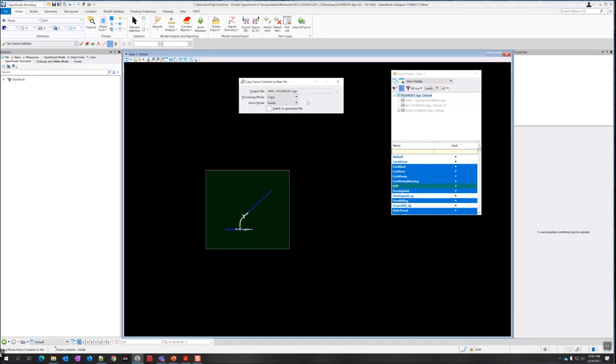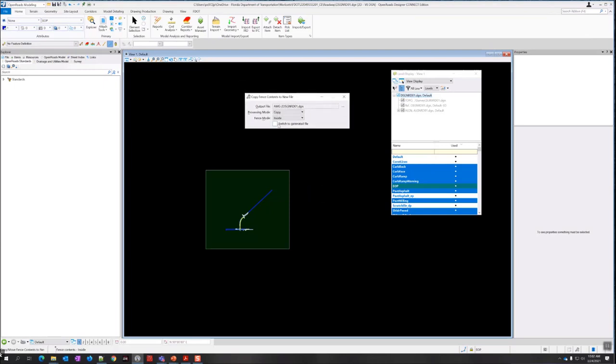So we're not done with the command here. There is an option also if you want to save it as a DWG. You can just go ahead and switch to the generated file and then save that 2D as DWG. For this one, it's not as crucial. It's an option if you want to create DWG for any reason. It's kind of up to you. If the contractor requests it, you can go that route. I'm going to show you how to do the save as DWG for one of these other files, so I'm going to skip it for this one. That's kind of an optional step. The steps are in the exercise here on page 5-5.